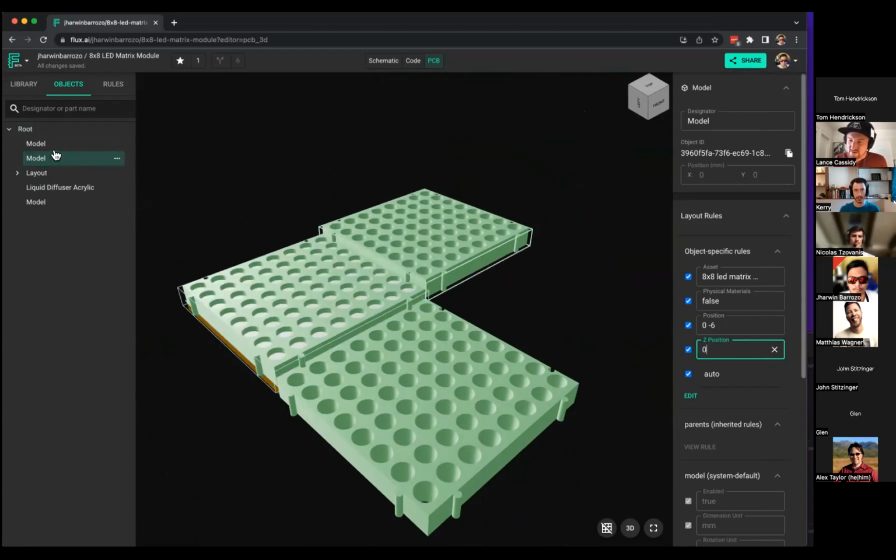Question from John, saying, I'm not sure we actually already answered this: is this project ready to upload to JLCPCB, or are we waiting for the airwire ground problem? It's not really a problem, but you could fork the unrouted project link that I shared in chat, and then once you fork it, you play around, move the components, and trace them all together. You could trace the ground also, just like a normal trace.